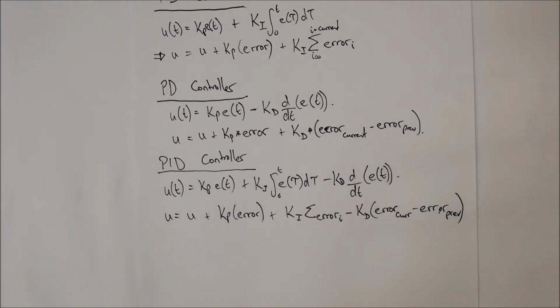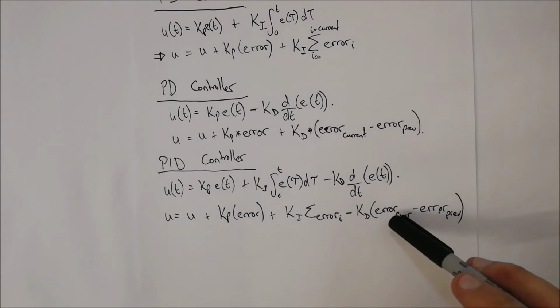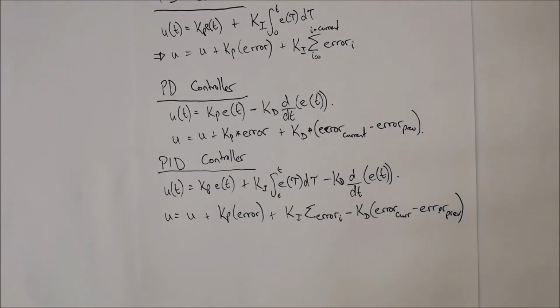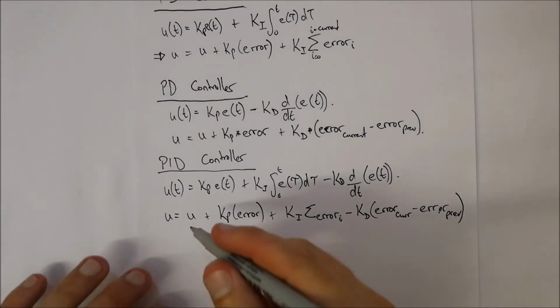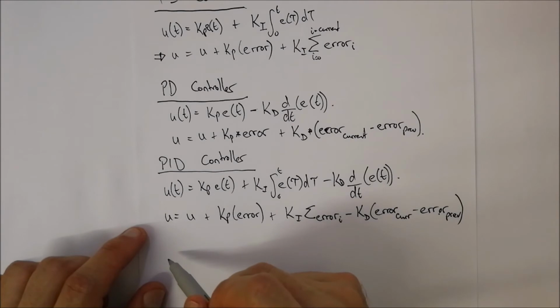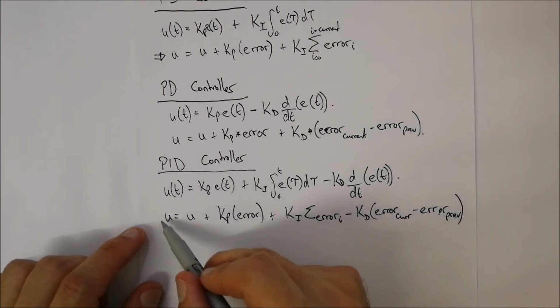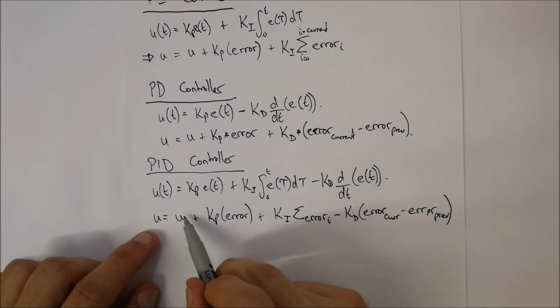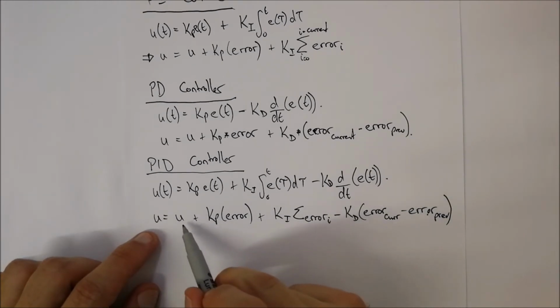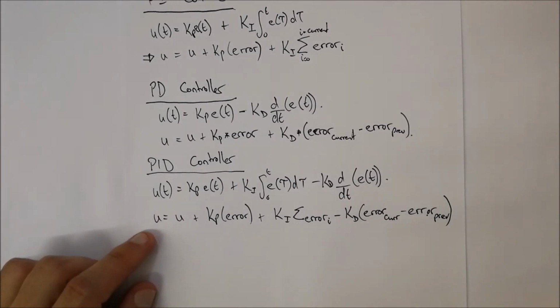Those are the expressions that you would commonly come across and use. Now again, a final line in these pieces is what essentially we're going to be looking at. Because our output often to some motor is PWM, we can say our new PWM value is equal to what the previous PWM value is, in other words u, plus this expression afterwards.